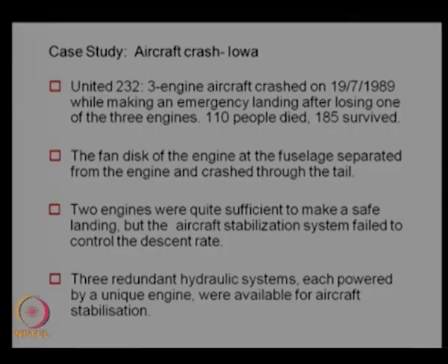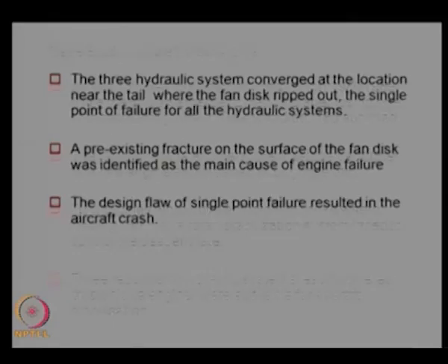But these 3 redundant hydraulic systems could not stabilize the aircraft, because the 3 hydraulic systems converged at a location near the tail where the fan disc ripped out, a single point of failure for all the hydraulic systems. So the point where all the hydraulic system outputs were converging at one location was exactly where the fan disc ripped through and blocked the hydraulic system.